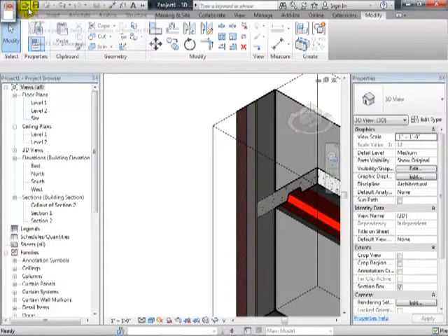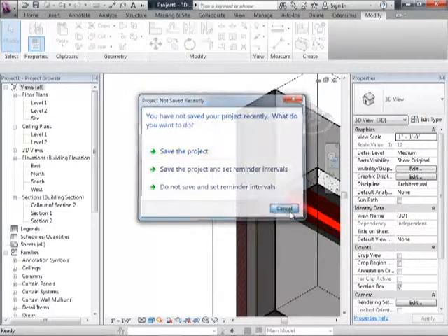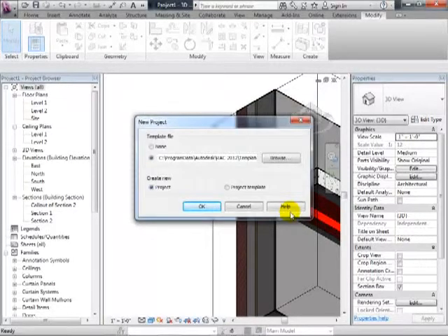Well, can I ask a question? Yes, you can, anytime. If you duplicate the wall, then it's going to just save it as you modify it? What'll happen, yes, if you don't duplicate the wall, let me cancel that, it'll replace all the existing walls that already have used that type.